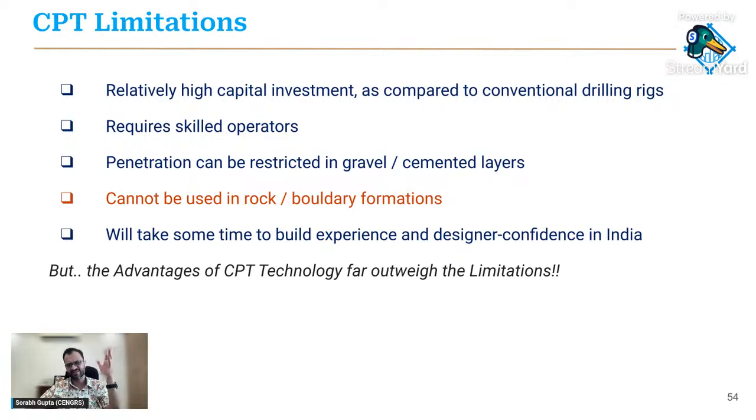Of course, people have had success pushing cones in gravel, even in some kind of weak rocks internationally, but you require higher pusher capacities, maybe 20 to 30, 35 ton pusher capacity for that. But largely, the main use case for CPTs would be in soil. So it is very good in India, not a problem, because if you look at the northern Indo-Gangetic plain, the coastal India, and so on and so forth, I think CPT is very useful in these kinds of geologies.